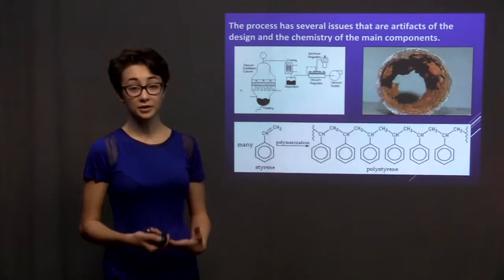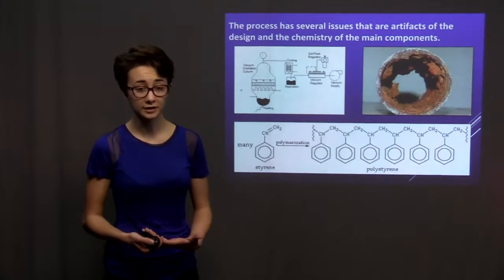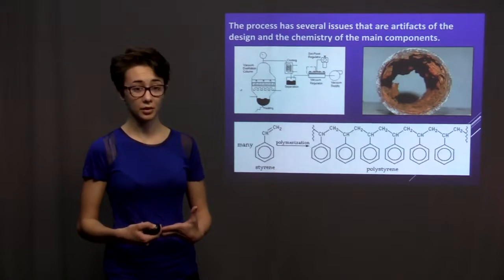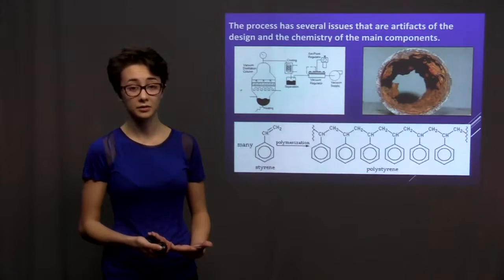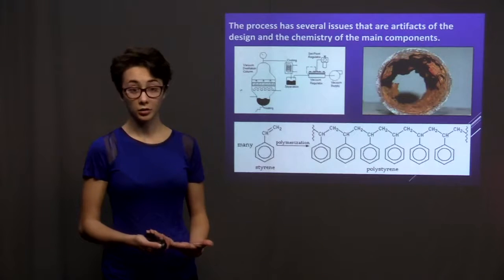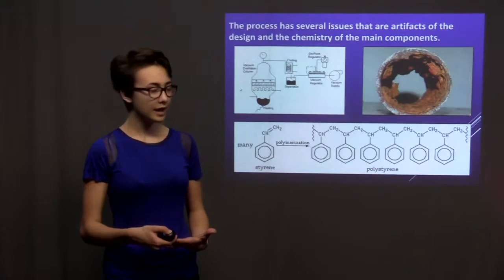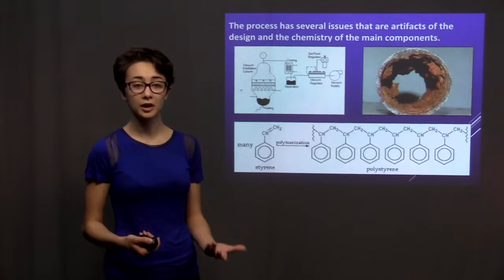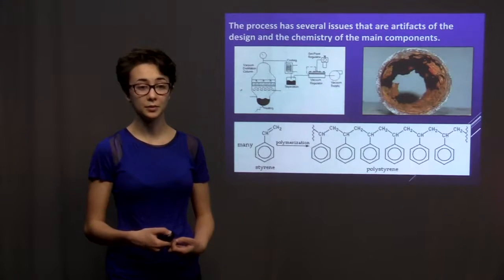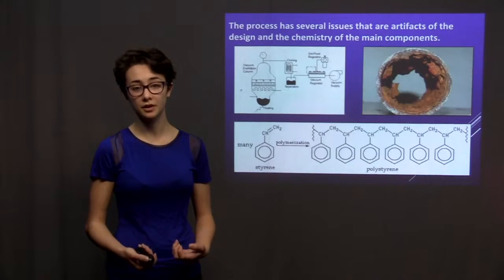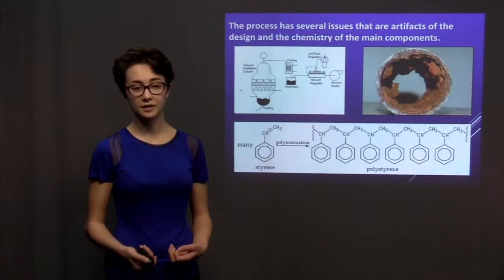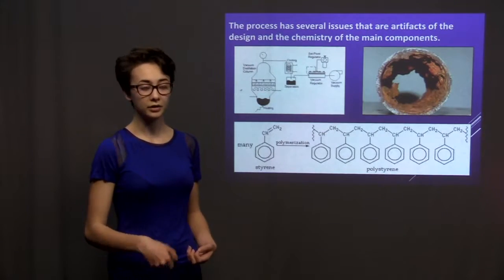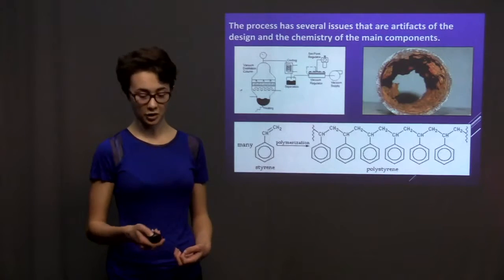Additionally, benzoic acid is present in our process, as well as some other acidic components, which would lead to increased corrosion of our equipment. And lastly, styrene monomer polymerizes at high temperatures, so we had to limit the temperatures of our final separations, as well as put refrigeration in place for our product.